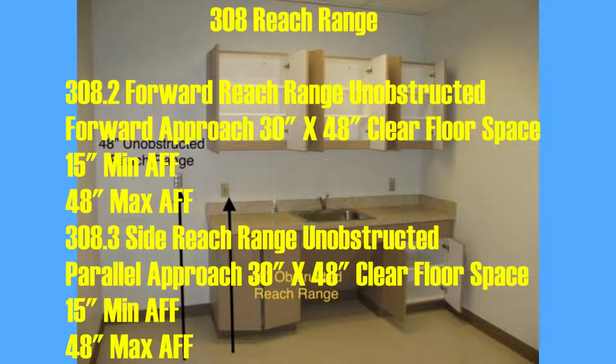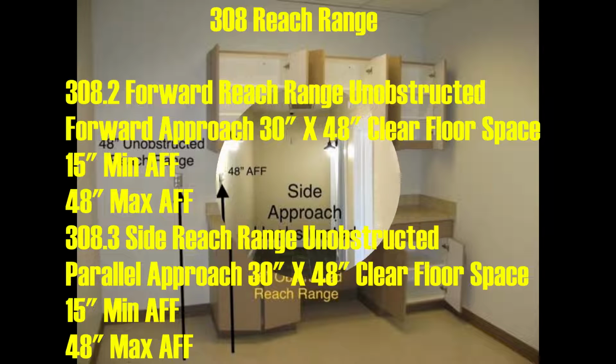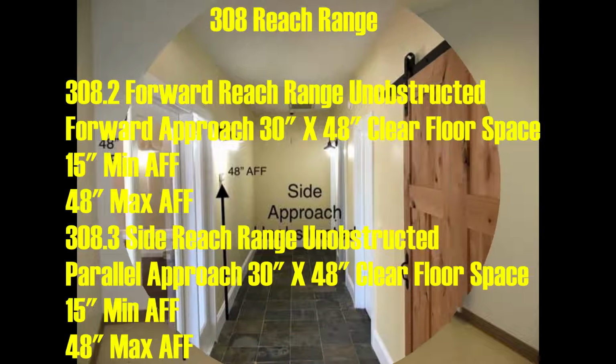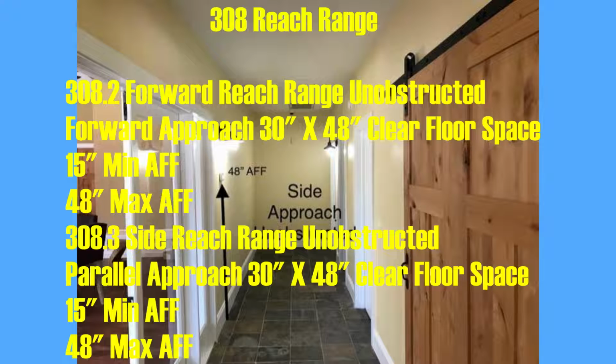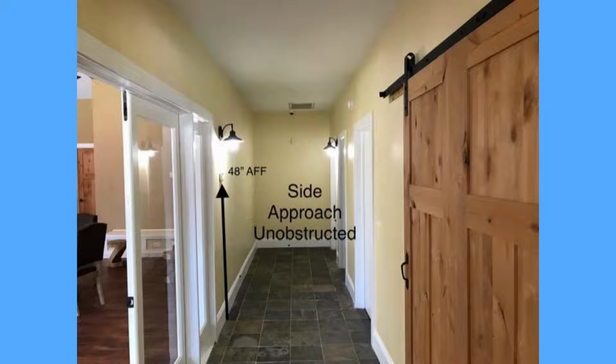Section 308, Reach Ranges. Forward reach range unobstructed with a 30-inch by 48-inch clear floor space in front of the element is 15 inches minimum above finished floor, 48 inches maximum above finished floor. Side reach range with the same clear floor space, 15 inches minimum above finished floor, 48 inches maximum above finished floor.